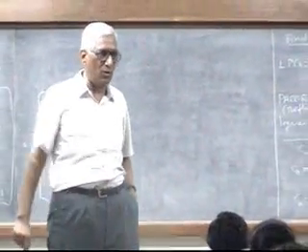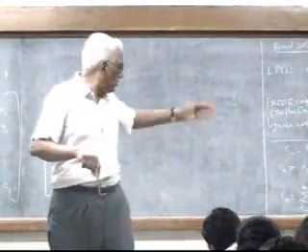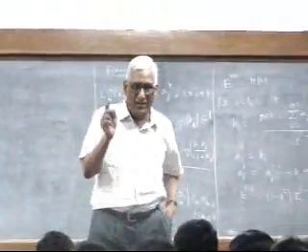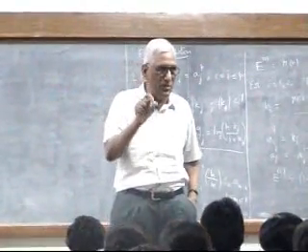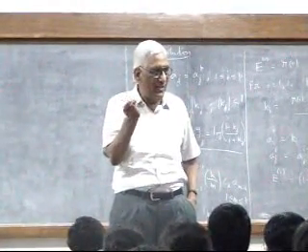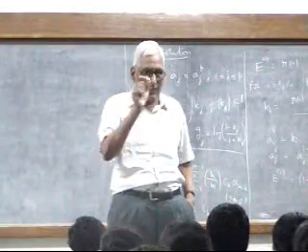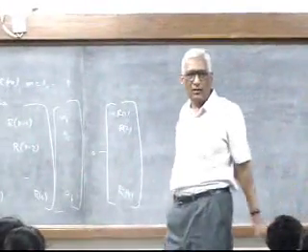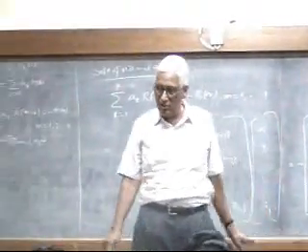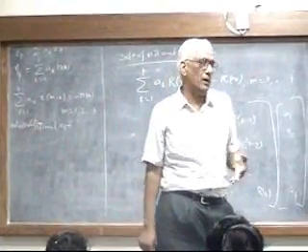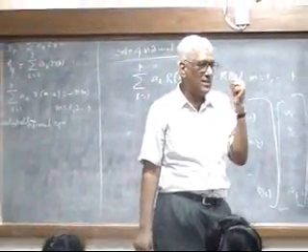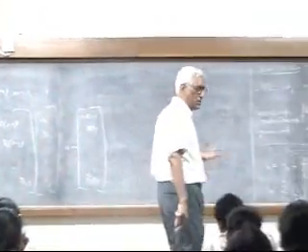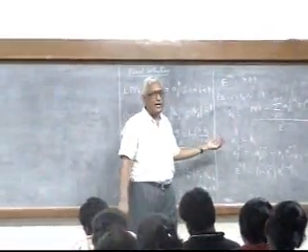In fact, it should not even be equal to 1. Somewhere in the loop you put mod k, and if mod k is greater than or equal to 0.99 or some limit you set, don't proceed further, set k equal to 0.99 and then proceed, so that you are ensured that your equations are always stable, the solution is stable. This is very important, especially because you can't say suddenly my speech coding has gone off. You have to worry about all of this. So that's why this inbuilt check is provided here.